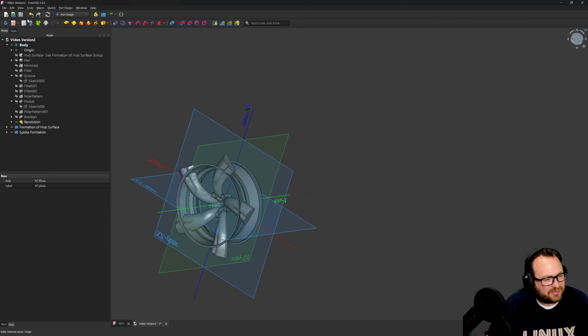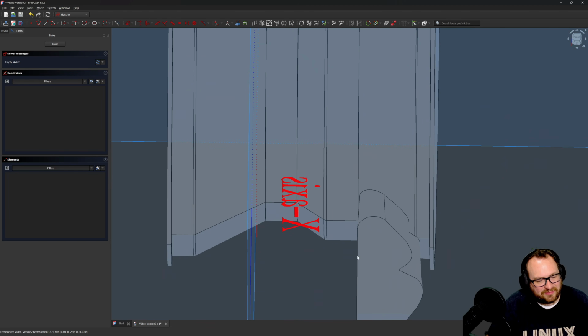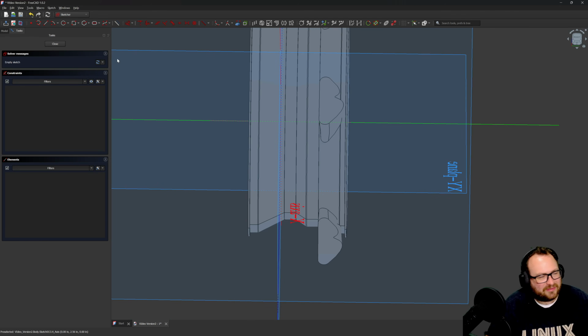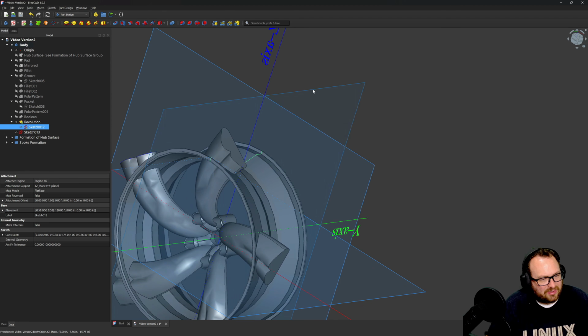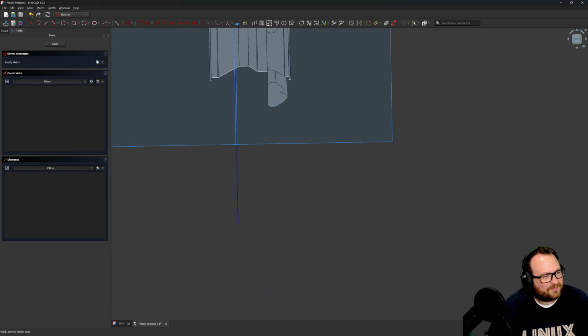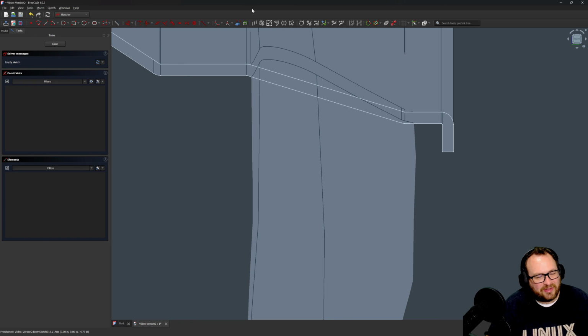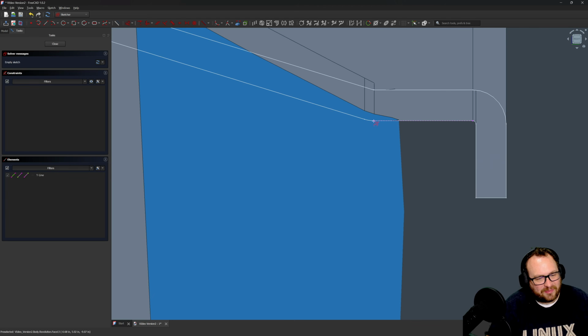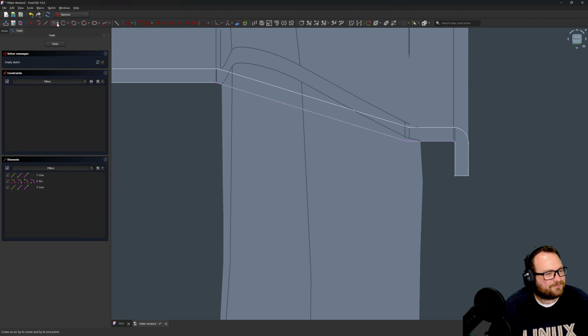So we'll grab this plane here. And now I want to import some things from my wheel. In fact, maybe I'll close this real quick and show my revolution sketch. And that's on a different plane, so I'll get rid of my sketch 13. We'll sketch on this plane. And trim here, trim our view so that we can see our sketch. Now I care about everything that is currently overlapping with that spoke sticking right out of our wheel.